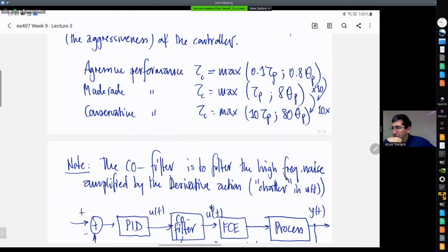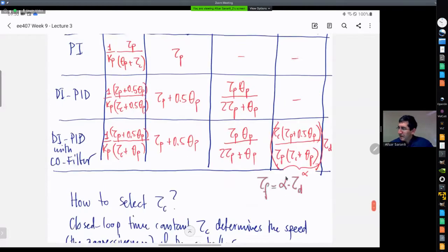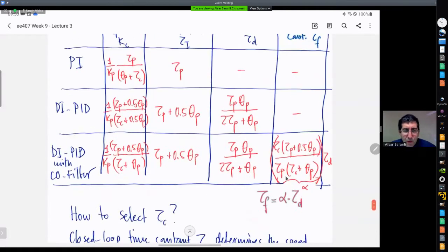So what we have done is that we discussed this new model, the first order plus dead time model, and based on this model we introduced certain design formulas for the PID controller. We haven't derived these formulas yet, and their derivation requires a bit more understanding of the time delay.